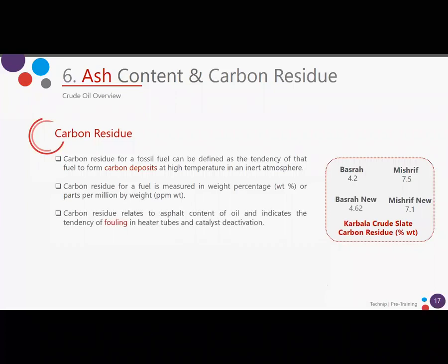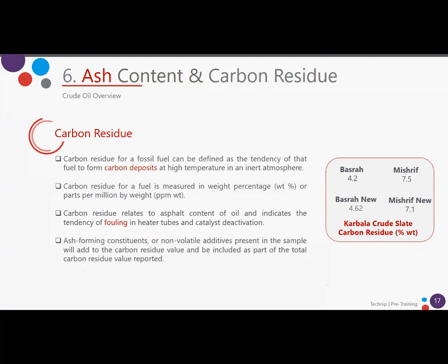Carbon residue relates to the asphalt content of oil and indicates the tendency of fouling in heated tubes and also catalyst deactivation. The ash-forming constituents will also be part of this total carbon residue.